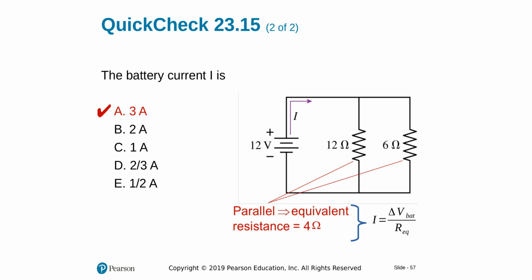Let's move a bit further here. I have this 3 amperes here. As it comes here, it will divide into 2. And it will not divide into 2 equal currents because I don't have 2 equal resistances. But I have this general Ohm's law, delta V over R. I know parallel arms has the same delta V. So this guy is same for 12 ohm and 6 ohm. Larger resistance gets less current.